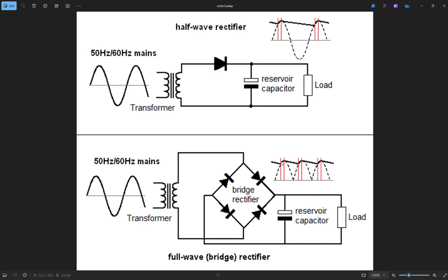But you can see these little dips and bumps, these are called ripples. They're like a water ripple. They're called voltage ripples. So eventually, your DC voltage should have fewer ripples, then you have a better quality of the DC voltage power supply. Okay, so we are applying capacitors and resistors that combined form what's called a low pass filter. So only low frequency components can pass, but high frequency will be attenuated. This is something you will learn in the future if you are in the electrical engineering major or minor.